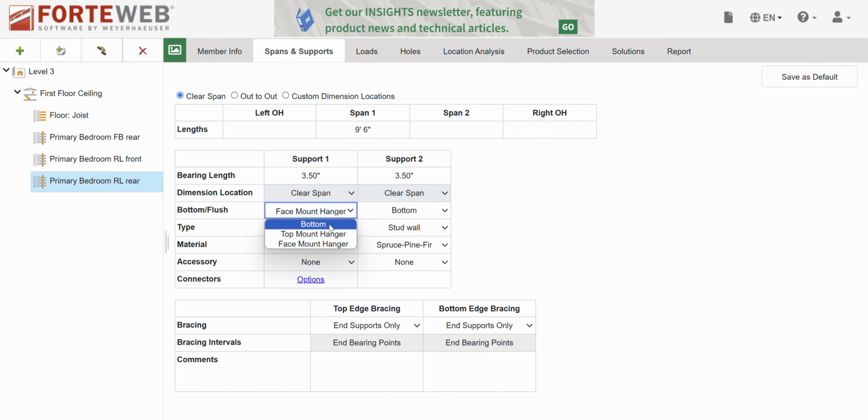All right, linked in, loads are populated, good to go. What do we need? Let's see, maybe 2 2x8s. It's a decently longer span. We're bending and deflection's still fine. Let's see what happens if we did 2 2x6s. We're getting up to 87%. That's kind of high, and 2x8s aren't that expensive, so we're going to bump up to 2 2x8s for this guy, and everybody's going to be hunky-dory. Copy, paste. 2 2x8, Southern Yellow Pine number 2. Great, that one's designed.